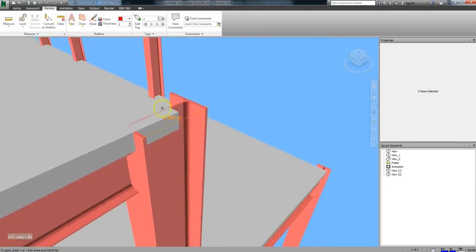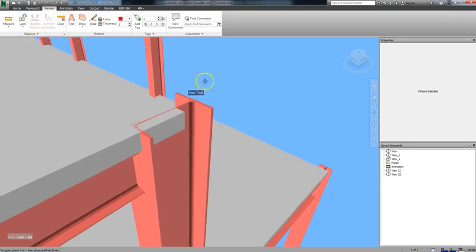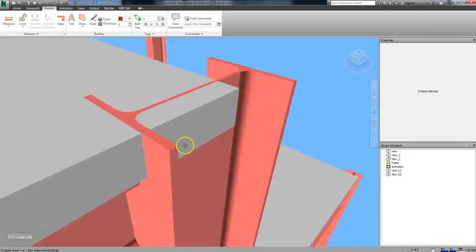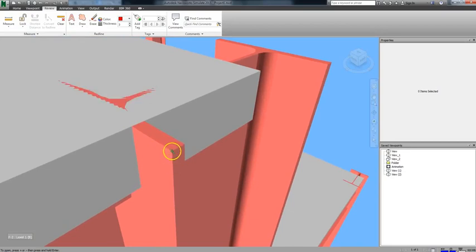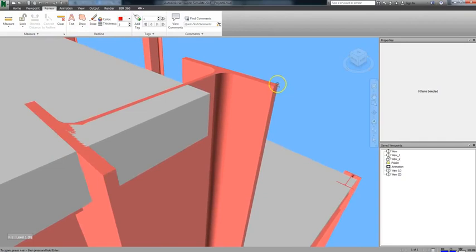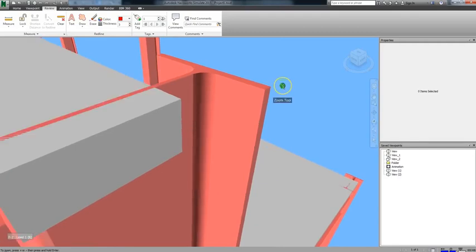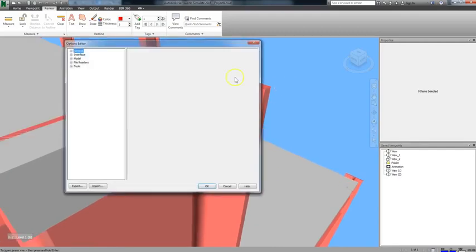If you want to delete a particular measurement, just make sure that it's selected, and then from the Review tab and the Measure panel, just click the Clear button. A quick note on that little cross or X that I've been talking about. You don't have to default just to that. You can always change how that looks, what its shape is, by going into the editor. So you can either go into the options editor, or for the keyboard shortcut, hit F12.